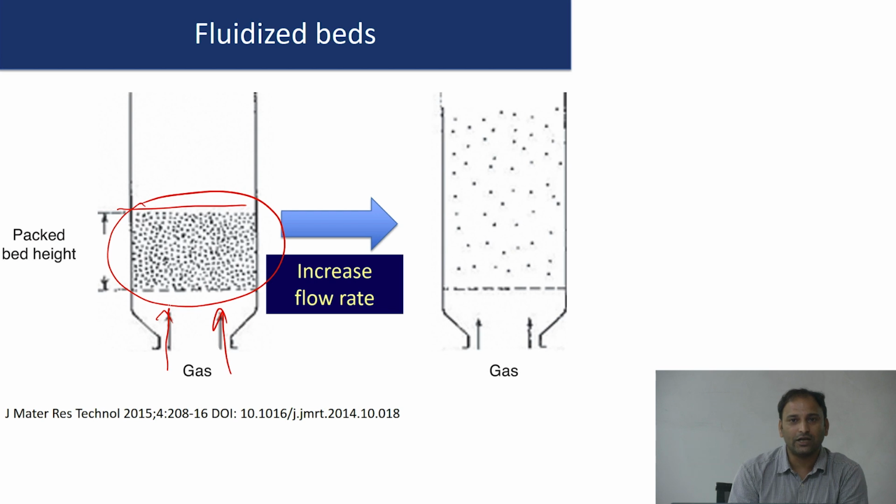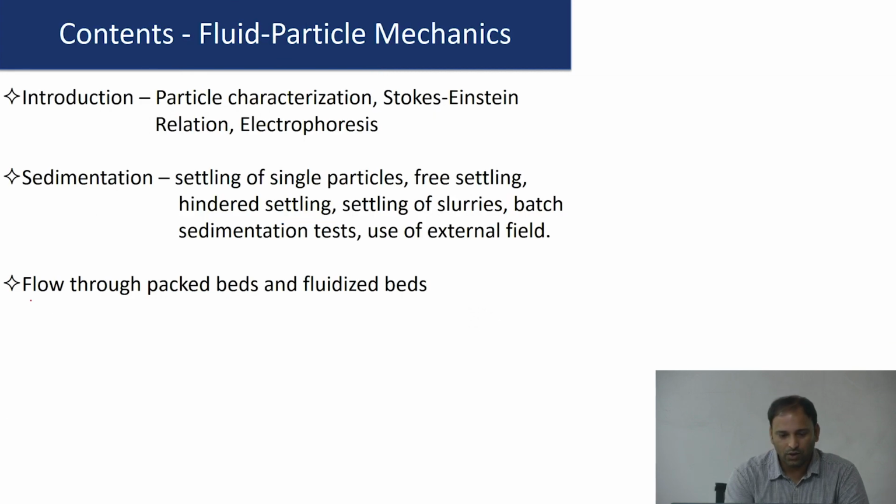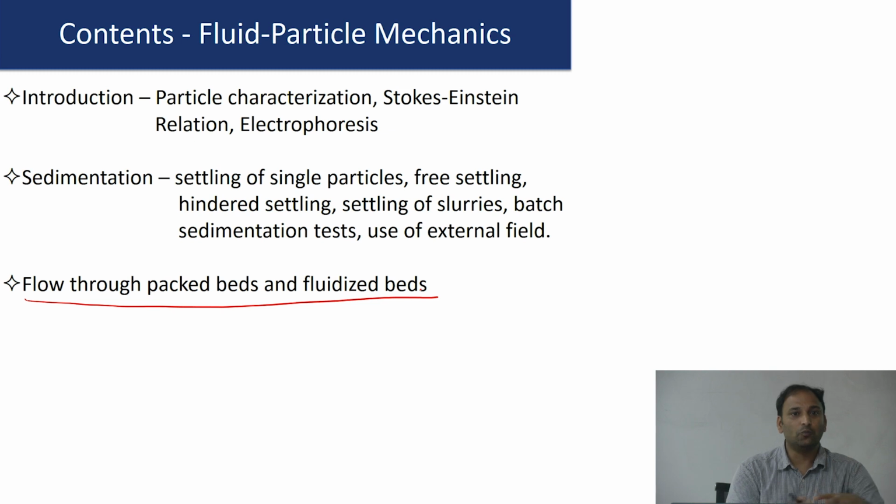If I go on increasing the velocity of the fluid that I'm sending from the bottom, at some point the particles are going to be in a nicely dispersed state. That is what is called a fluidized bed. So we're going to look at flow through packed beds and fluidized beds. We're going to analyze flow through packed beds in terms of what we've learned about flow through pipes. We're going to use that concept to look at flow through packed beds, and then look at pressure drop and things like that.